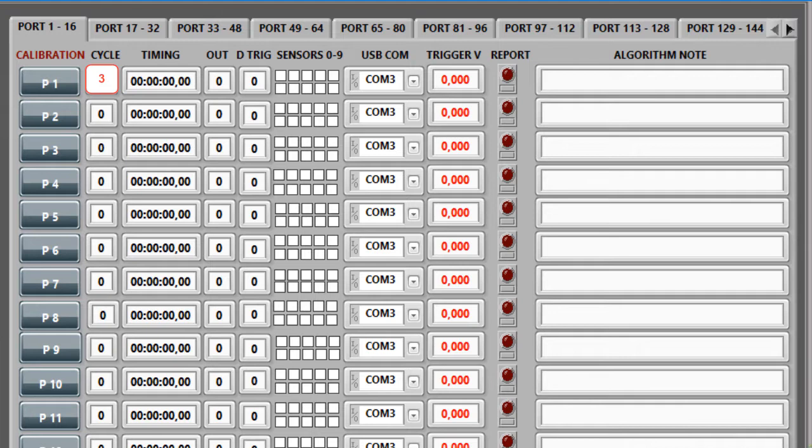This situation occurs when the algorithm of the entire project begins with a call to the input port and the module does not have time to activate its functions at the hardware level, with a high probability of spontaneous reset of the first call. We got around this situation by launching the port 3 times, which does not affect the further progress of our scenarios.